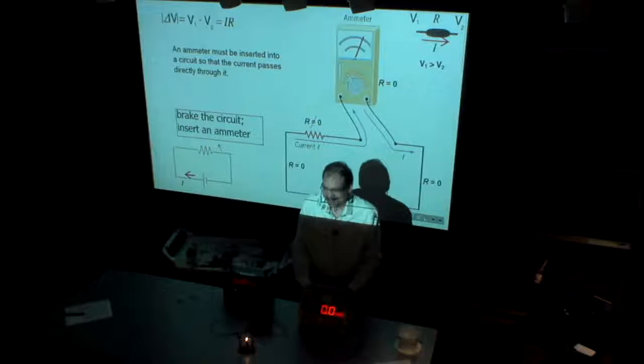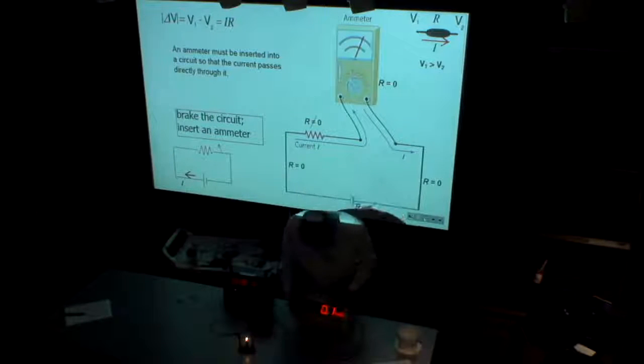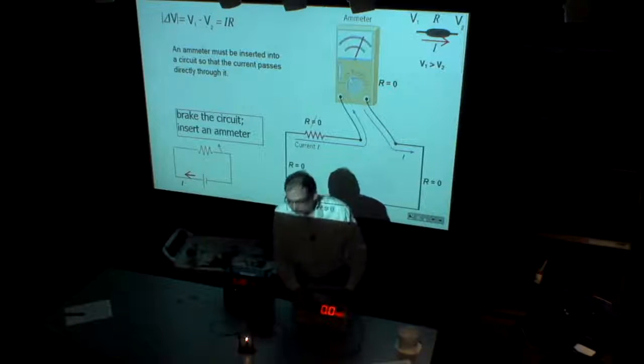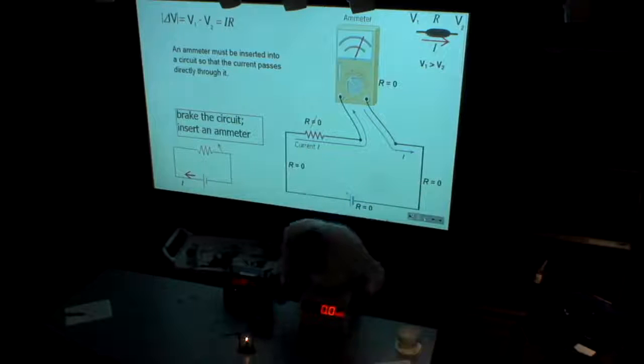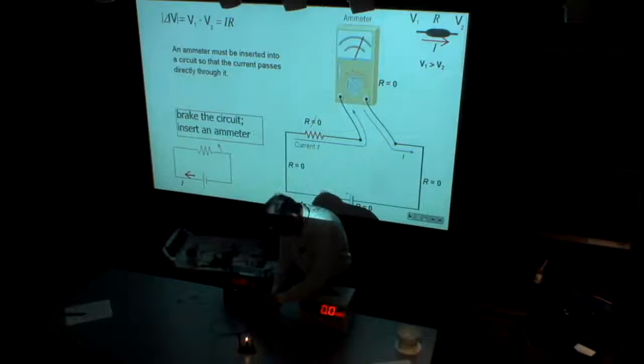We call them DC and AC, and DC means direct current. Direct current means it's constant in time, and that is happening when we use the battery. AC means alternating current. Alternating voltage is what we use in a power outlet. It changes in time. So we have to use settings accordingly. If we use a battery, we have to use a DC setting, direct current. So now I have to break the circuit, to break it for you.